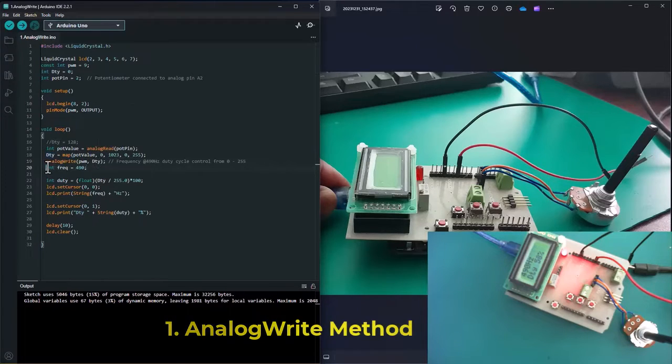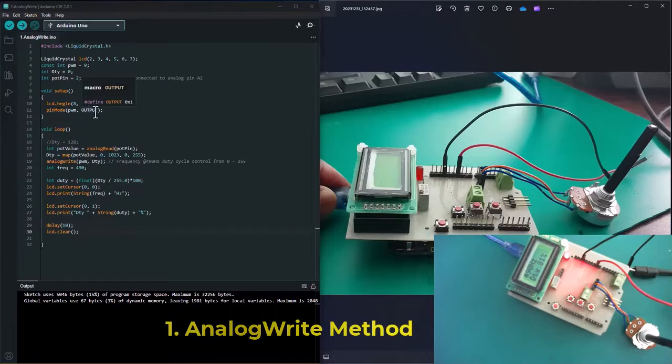Now from line 20 down to here is basically just me displaying whatever you see on the screen when we control and we are getting. Now, if you remove everything down here, it's still going to work. Obviously, it's going to work. The only line of code you need here is basically analogWrite. So that basically means your PWM pin must be set up and the duty cycle reading from your potentiometer is set up. So you can complete this code with basically just a few lines. Otherwise, if you want to be a bit fancy like me here, you're going to have all these other codes here.